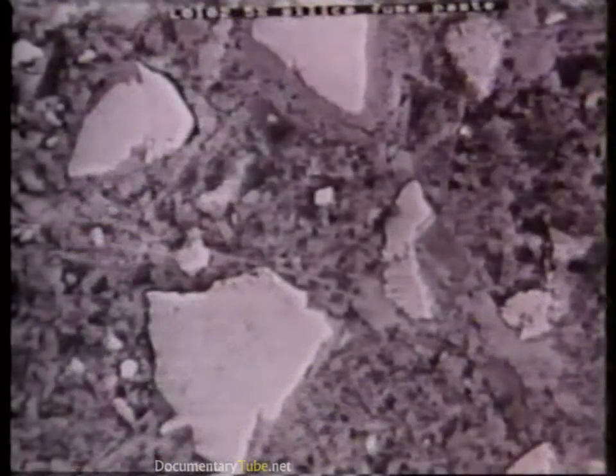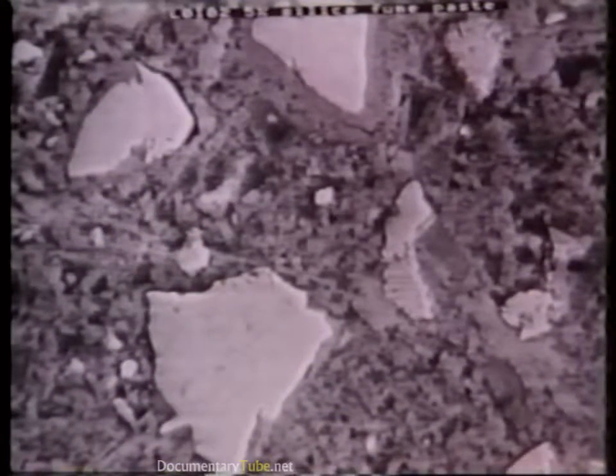As this process repeats again and again, the microstructure develops, building bridges between particles that provide strength. This has proved valuable because it allows researchers to test conditions and make measurements that are difficult to achieve in real life. At the end of the hydration simulation, the structure of the hardened cement paste is very similar to that observed under the microscope.